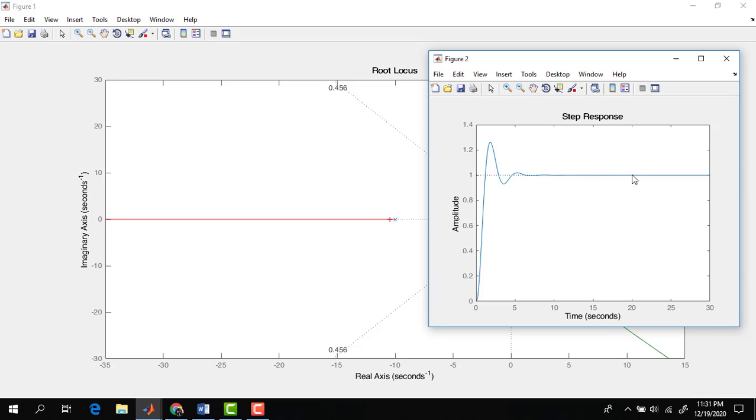So for these cases we will not actually use a lag compensator. It's just a demonstration process, so anyways we are using this function. But in practical cases you will need to use a lag compensator for those functions whose step response will not give you a perfect 1. Let's say after some time the steady state value is 0.8. So there is a big gap between our desired result and our achieved result. In those cases, we will mainly use a lag compensator.